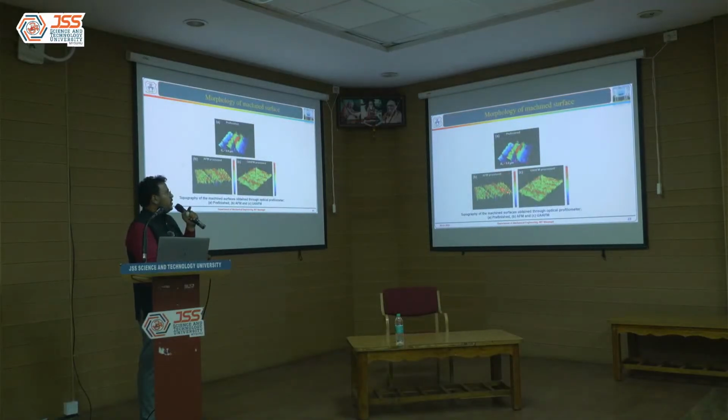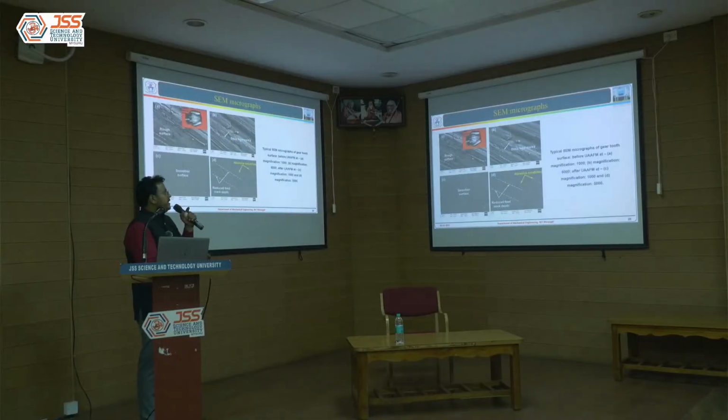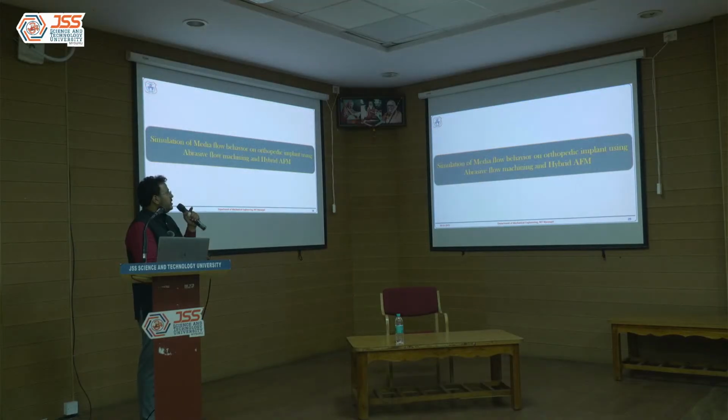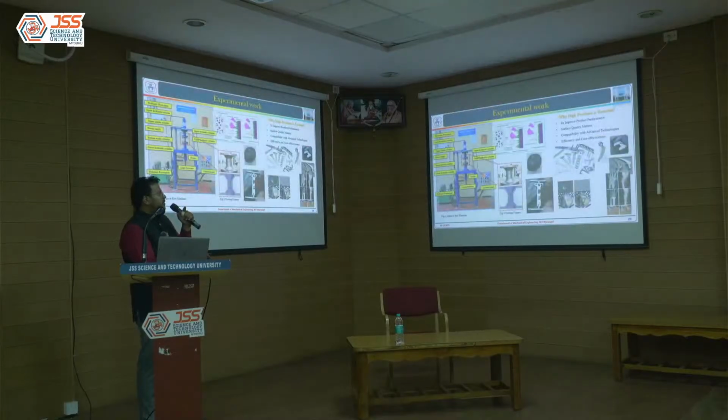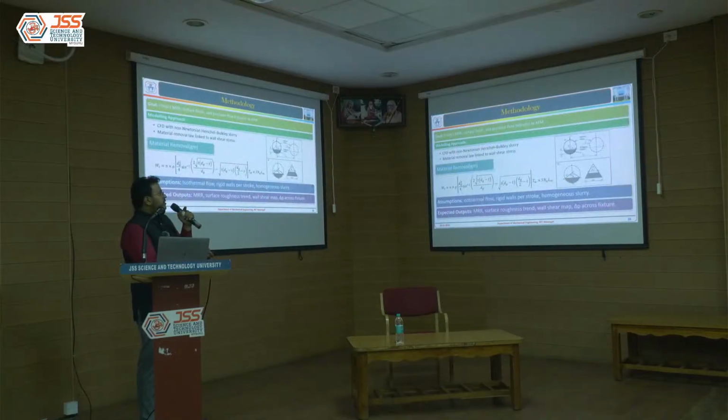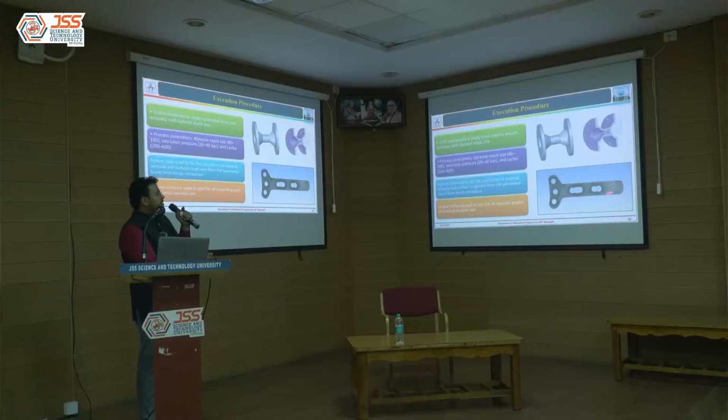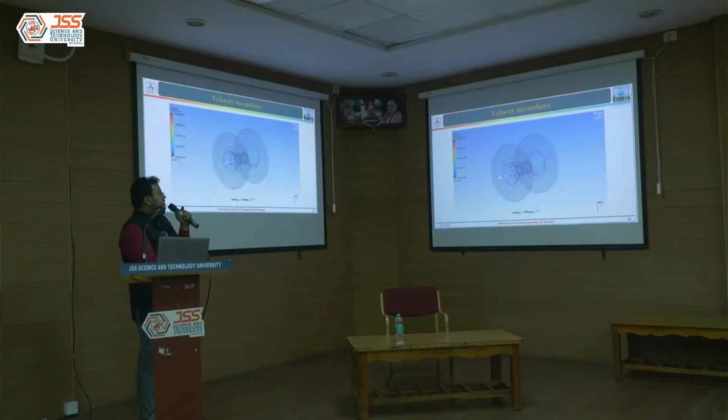And we recorded the morphology of the machined surface under an optical microscope, and analyzed how the deep feed marks of the bevel gear and the rough surface become smoother using ultrasonic assisted abrasive flow machining. Right now we are working on simulation of media behavior on an orthopedic implant using abrasive flow machining and hybrid AFM. Here I will show you the fixture developed, and this is a mesh model of the workpiece, and you can see the simulation for velocity streamlines inside the fixture.